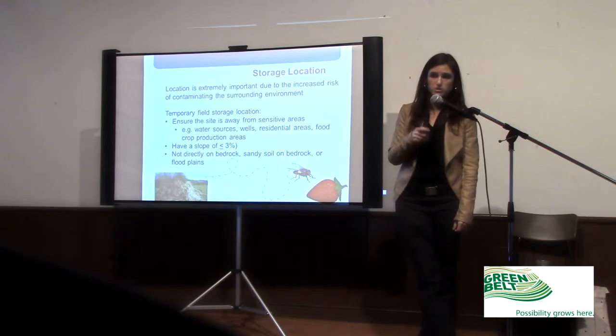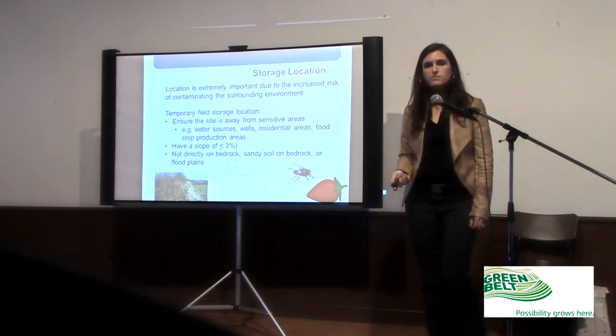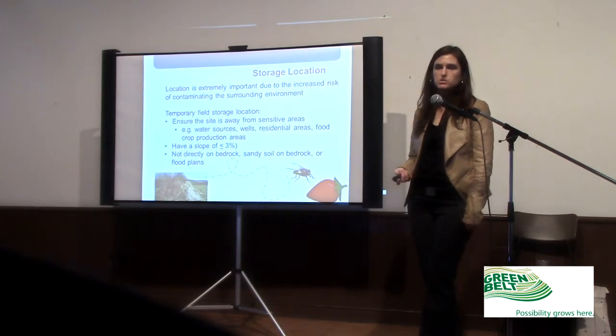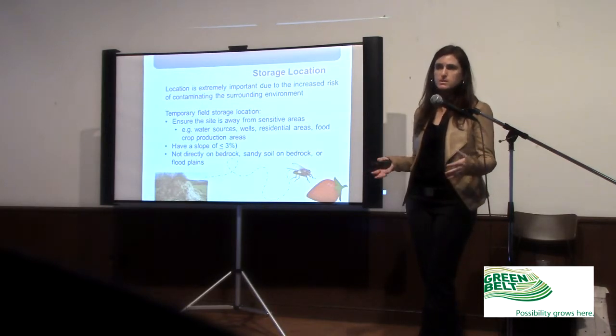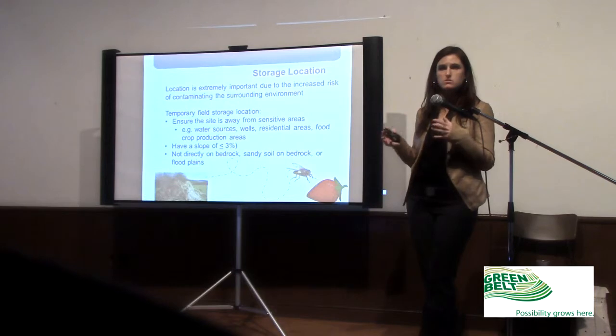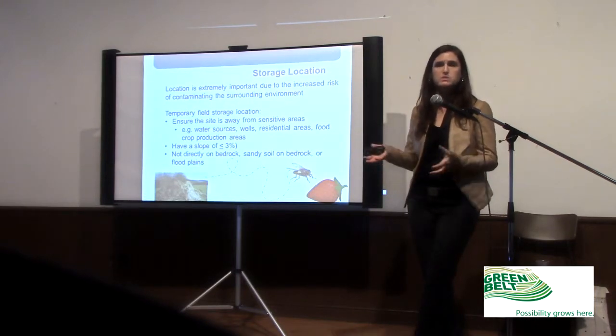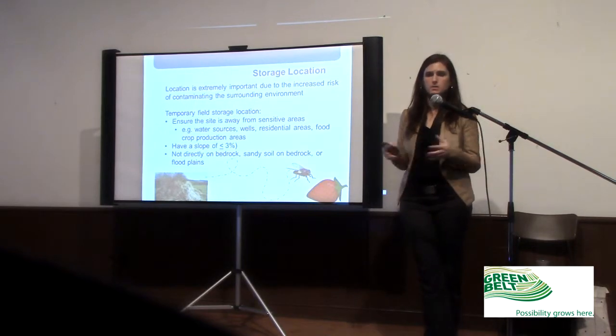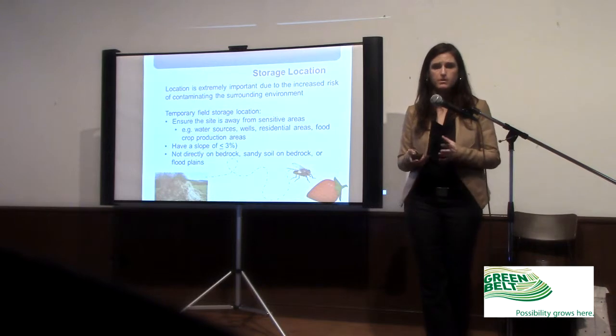So we kind of just touched on that a little bit. If you do have a temporary field storage location, you really want to make sure that it's away from any of those sensitive areas, residential areas, because it's not covered. There's not usually a berm or something to divert it if water comes in contact with it. So the more distance that you can have that's practical for you, the better.